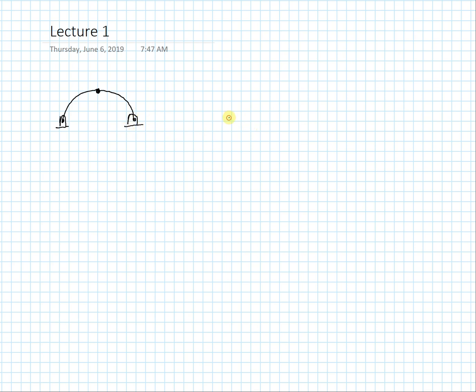And if we were to draw the free body diagram for this arch by separating out the structure at the location of all the hinges, we would have these vertical and horizontal forces, these ones. The counterparts to those would be in the opposite direction, and these reaction forces. So if we're looking at this structure, this arch structure with the hinge in the middle, we're going to have 6 reactions in total, as shown in this free body diagram. This is an FBD. So R is equal to 6, and N is in fact equal to 2. We're looking at 2 elements. We have divided the structure at the location of the hinges. And so we can say that R is in fact equal to 3 times N, thereby this structure is determinate.